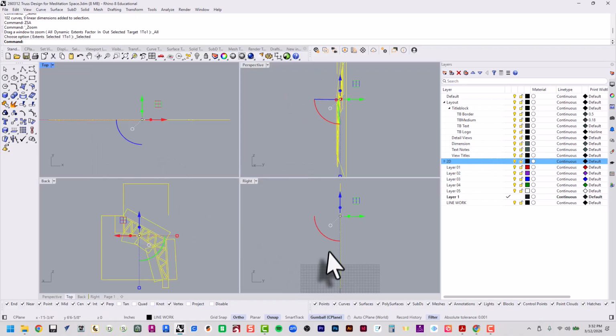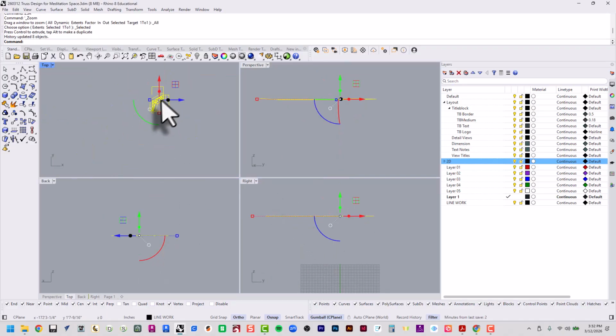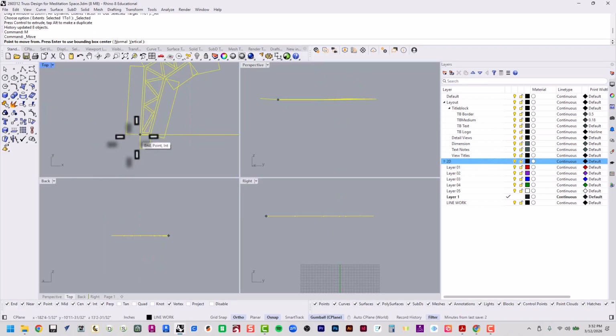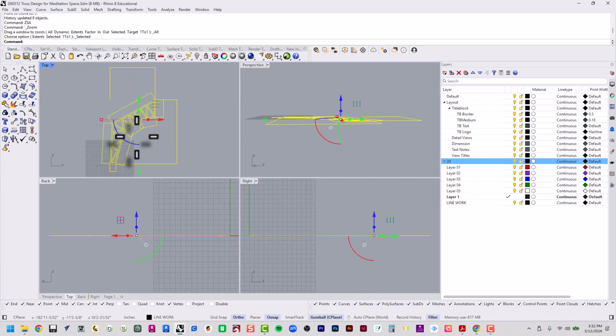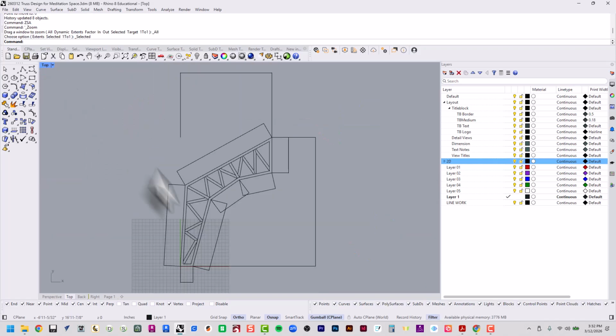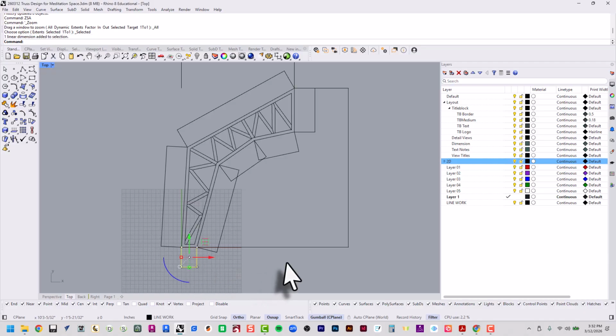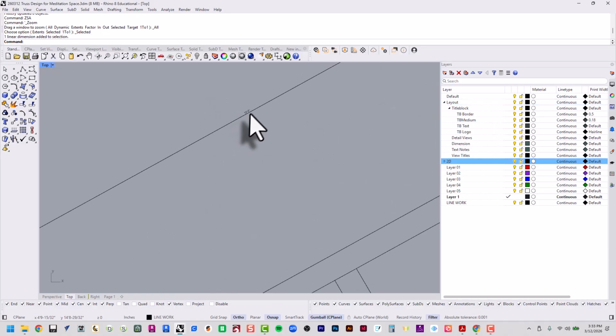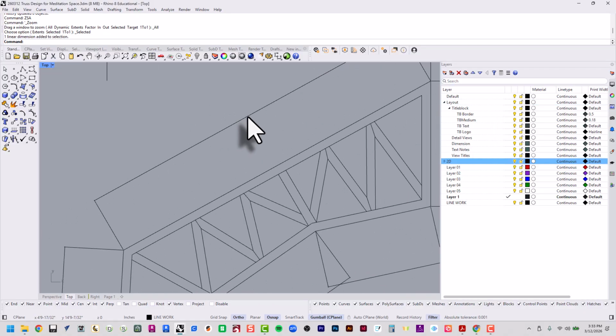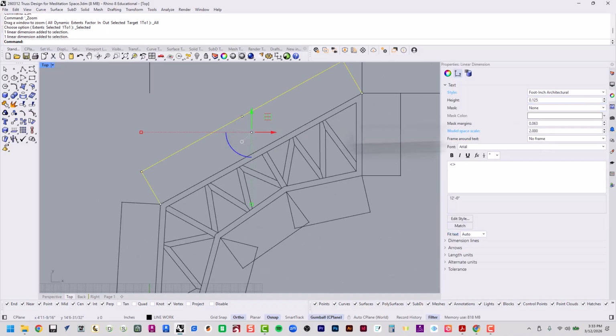Flip it down, and then this time I'll move it to the ortho view. ZSA to zoom select all. So we've got a bunch of dimensions. Here's my dimension line. It's really hard to read these dimensions right now because they're so tiny on my 1:1 scale model view. If you select one of these dimensions and go to properties, you'll see it's 1/8 inch in height.